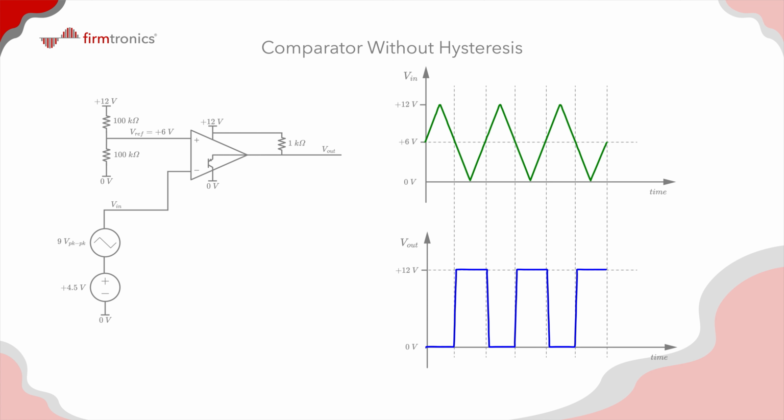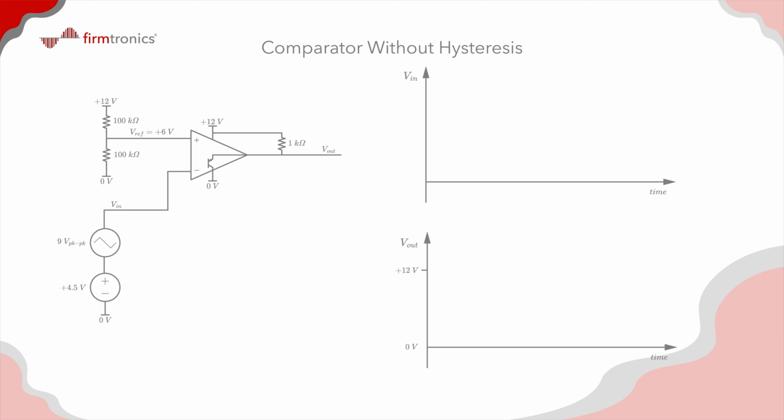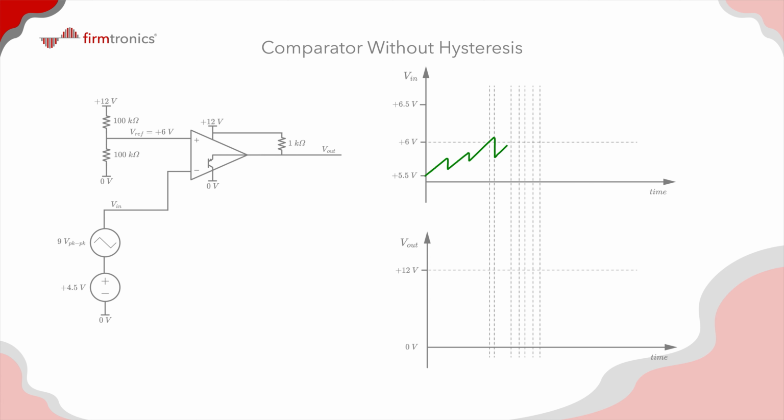The comparator input can be connected to a temperature sensor or a light-dependent resistor. In this configuration, the output from the sensors carries a small amount of noise on the signal. This can be observed if we zoom into the millivolt range on the signal and look at it on the oscilloscope. The noise is generally an addition of many sources, such as thermal noise, electrical interference, and power supply instability. This can be challenging to remove completely with hardware using filters, etc.